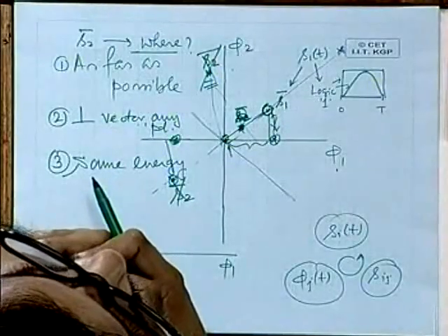So, to design a good modulation scheme and then incorporating the corresponding very important issue of good demodulation scheme, it should be good to choose signal points very intelligently, in an ordered fashion, such that the problem of detection is well understood, is feasible without much complexity, and we get the best possible result in decision making. The second issue is that we should also ensure that the average transmission power is minimized. Like, instead of choosing S1 here and S2 here, one could choose S1 here and S2 here. What is the essential difference? The second one is unnecessarily asking for larger transmission power.